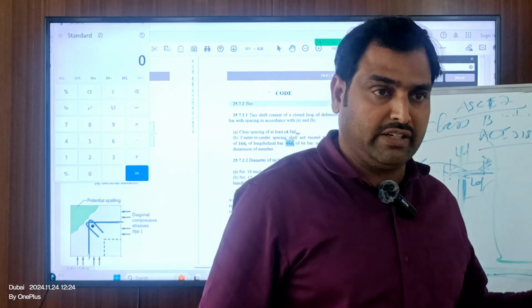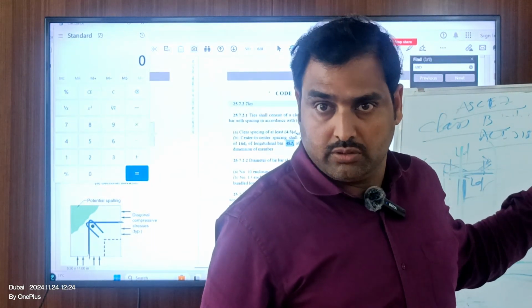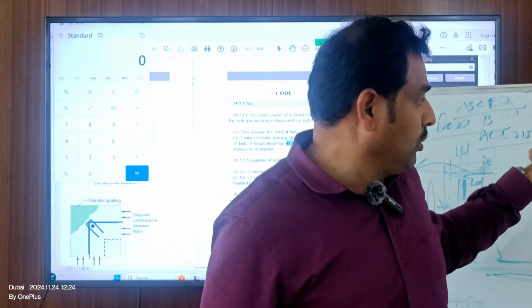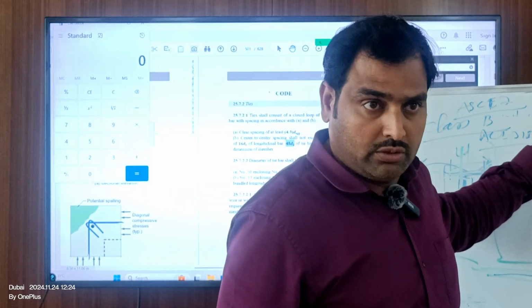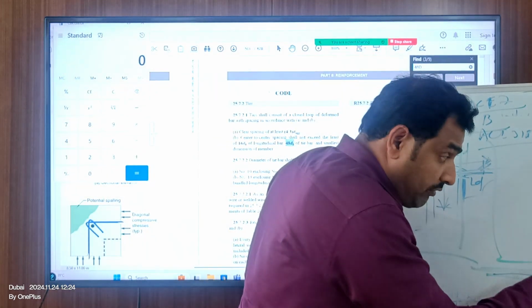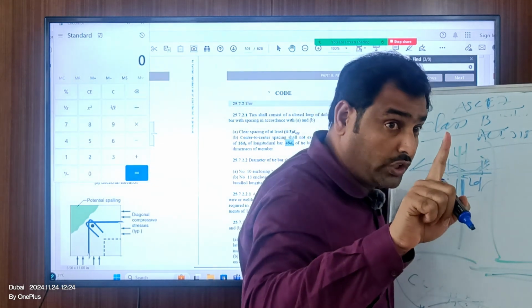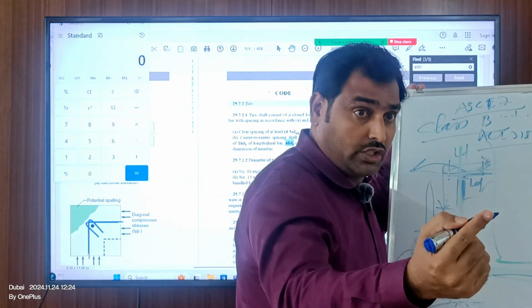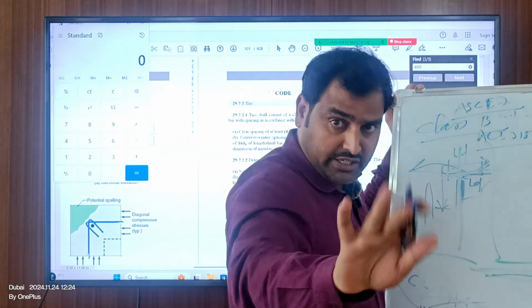Actually, in the manual calculation I showed how to calculate the effective height of the columns, right? Effective height of the column. When you're talking about simply supported, the bending is going to start from here to here, the full height of the columns, right? When you're talking about fixed connection, if you don't release it in your structural model, it will be considered as a fixed connection.